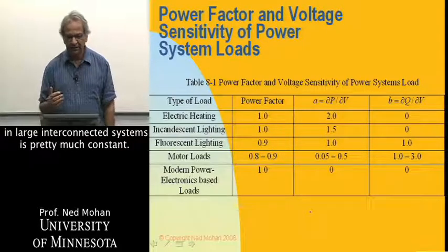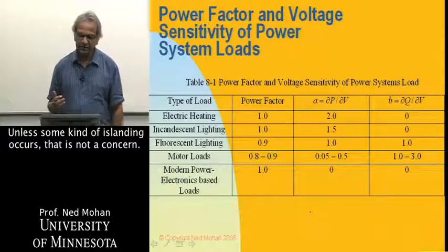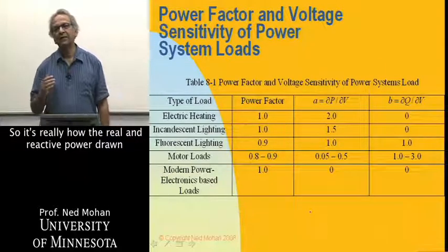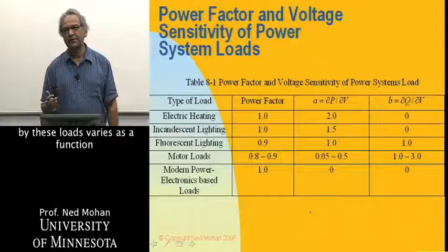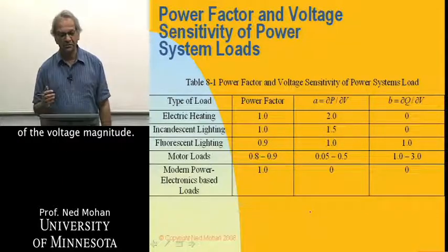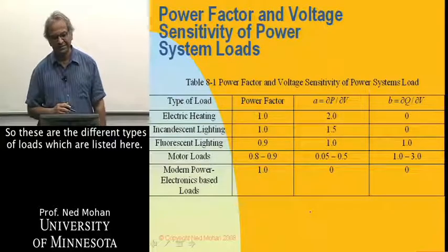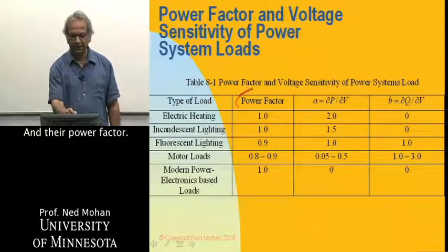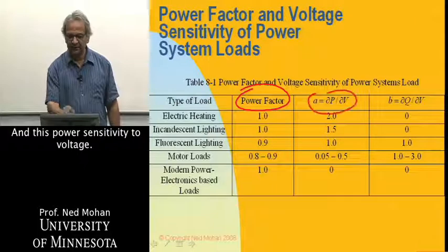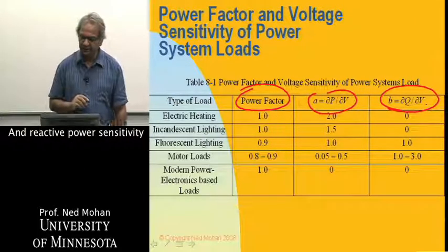So unless some kind of islanding occurs, that is not a concern. So it's really how the real and reactive power drawn by these loads varies as a function of the voltage magnitude. These are the different types of loads which are listed here, and their power factor, and there is power sensitivity to voltage and reactive power sensitivity to voltage.